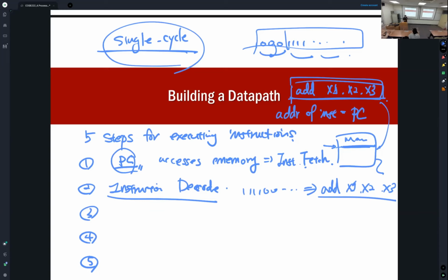If we see this instruction add x1, x2, x3, then we know that this instruction requires operands from the register file. A processor needs the operand data from the register file, and the location of the registers is specified by register numbers x2, x3. So the instruction decoding step also includes reading operand data from the register file.